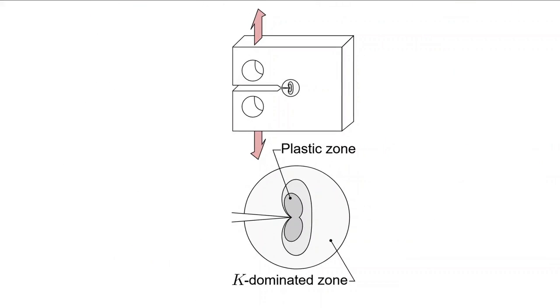We know that a far field stress acting on a crack of a given length can be related to a stress intensity factor, K, through a proportionality. So it stands to reason that if we want a material property, all we need to do is put some stress on a predefined crack and we can get a K, and therefore come up with some engineering values as to how susceptible a given material is to fracture.